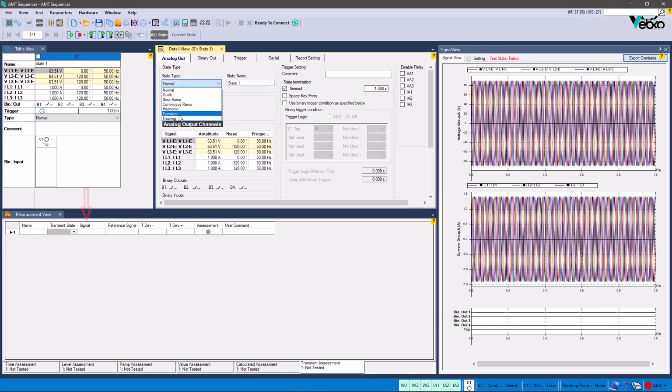In the Signal field, a binary signal is selected for comparison with the reference signal from the Comtrade signal. In this field, the list of all binaries activated in the hardware configuration are displayed, and one of them should be selected. In the reference signal field, the reference signal is selected from the Comtrade file. By clicking on this field, all the existing binary signals in the loaded Comtrade file are displayed.